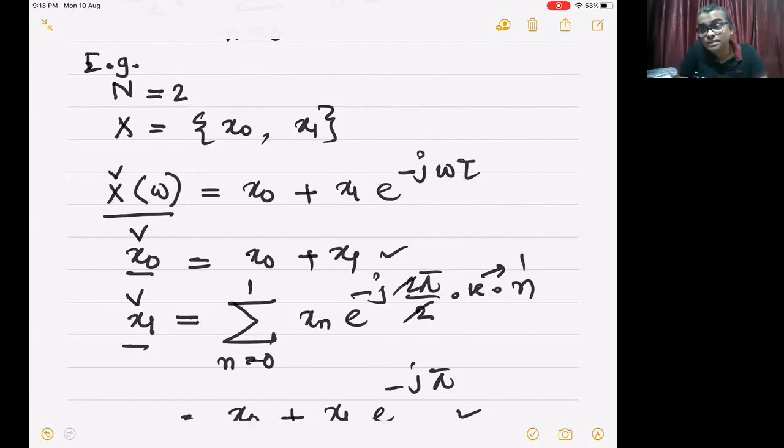Yeah, this is how data is compressed. So for a large mixture, if you take its Fourier transform and send only the small frequency components like this, then the receiver will be able to reconstruct the signal to a reasonable degree of faithfulness, without actually getting all the information, as in the time domain signal.